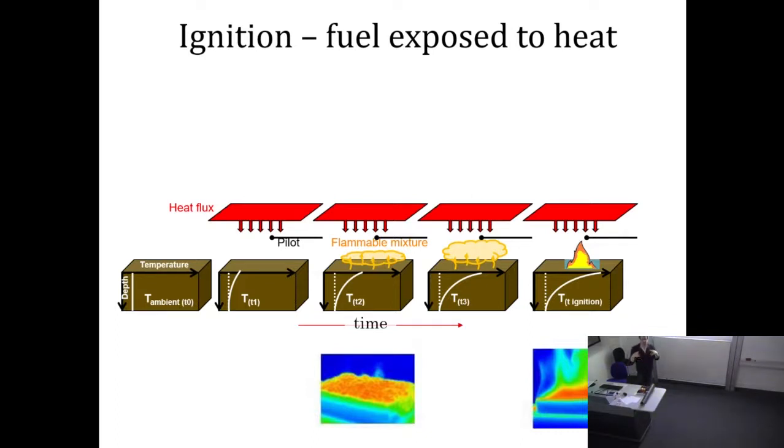This cloud of pyrolysate mixed with air that is flammable and finds an ignition source, it will be maybe a second of a premix flame. But then this flame will establish over the surface of the fuel, and it will become a diffusion flame, and the radiation from the flame, especially from the inside, will actually pyrolyze more fuel that will feed into the flame. And now it becomes more like a candle, where the candle itself and the heat from the candle is actually the engine that is providing the gaseous fuel out of the solid fuel. And then it will be a turbulent diffusion flame for the rest of the process.